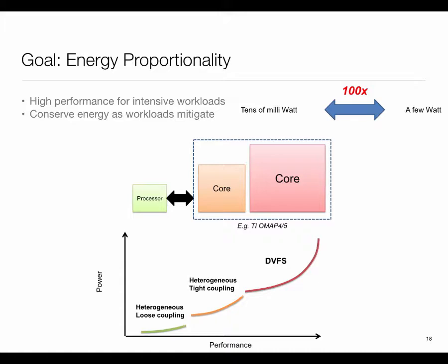Like iPhones have this M7 processor, which is really a Cortex M3 chip, and that is how it keeps track of the accelerometer and some of the other inertial sensors which need to be active all the time. Other devices have the same thing. Snapdragons also have several Cortex M3s inside the chip, which they do not expose to the programmer, but Qualcomm uses them for sensor processing and so on. Let's see, what other examples can I give of this? DSPs are other examples.